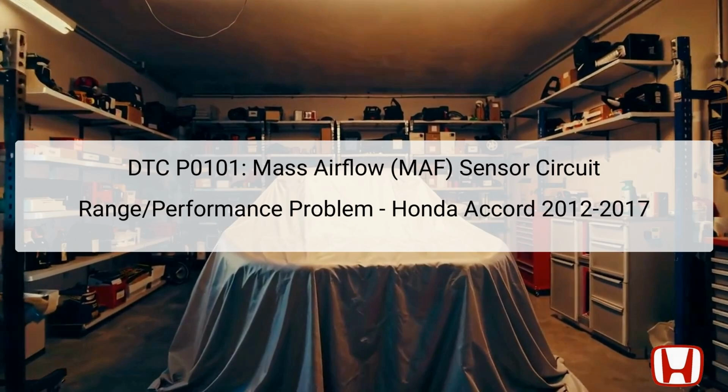The Diagnostic Trouble Code, DTC P0101, indicates a concern with the mass airflow MAF sensor circuit. This sensor plays a crucial role in engine management by measuring the amount of air entering the engine. The Powertrain Control Module, PCM, utilizes this data to adjust fuel injection for optimal performance. Any malfunction in the MAF sensor can lead to incorrect air-fuel mixture and engine performance issues.